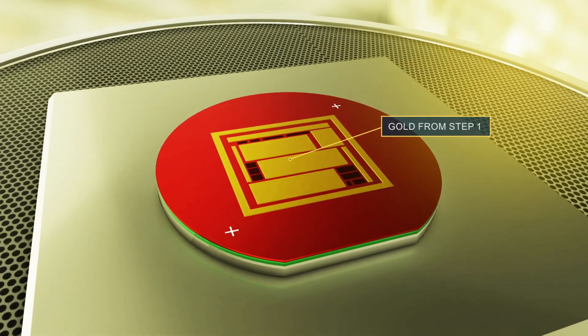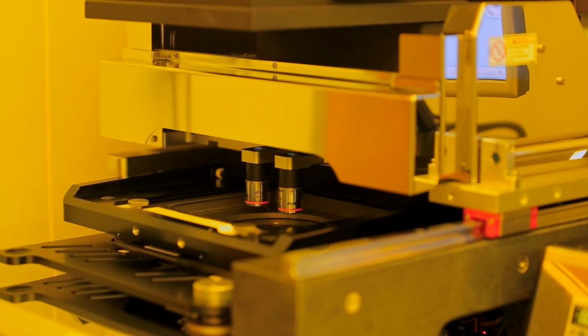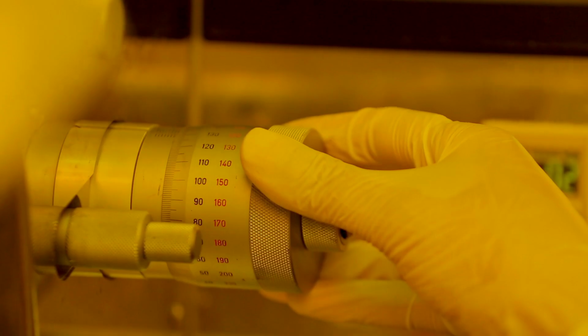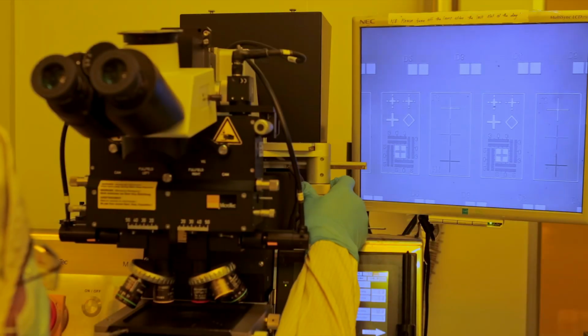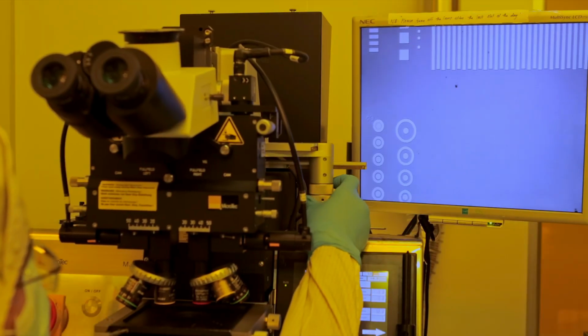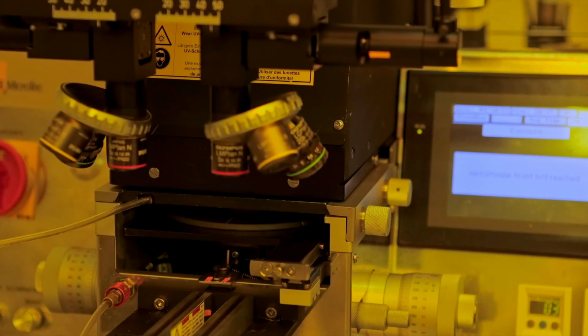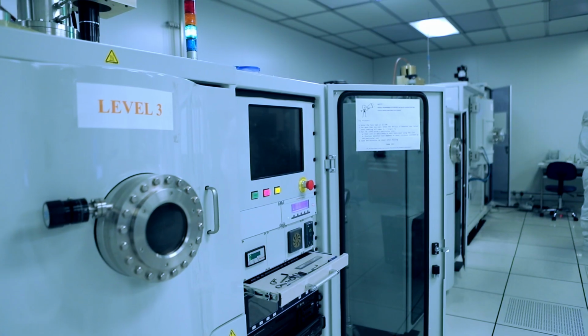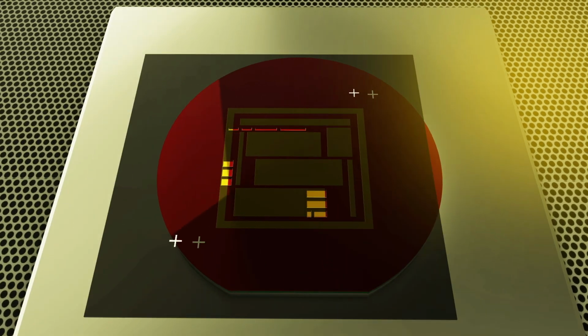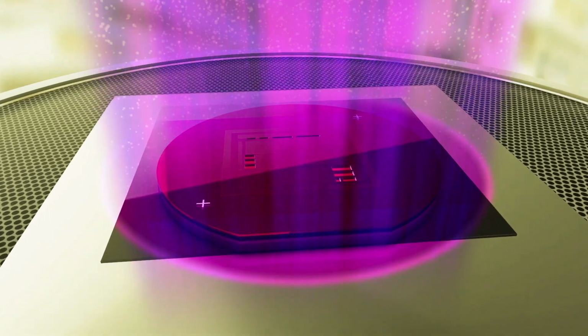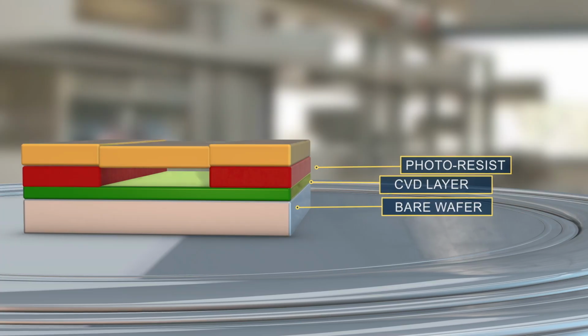The device or circuit will then not work properly. The PR is exposed and the metal is deposited again. Post liftoff, the second pattern with a definite relationship to the first one is now realized. We have now gone through 2 steps.